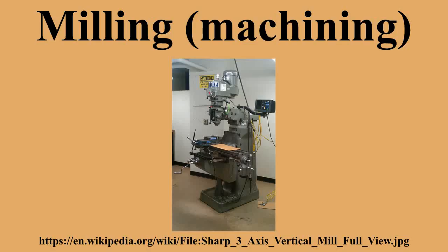SK and HSK tooling, sometimes called Holoshang tooling, is much more common in Europe where it was invented than it is in the United States. It is claimed that HSK tooling is even better than BT tooling at high speeds. The holding mechanism for HSK tooling is placed within the body of the tool, and as spindle speed increases, it expands, gripping the tool more tightly with increasing spindle speed. There is no pull stud with this type of tooling.